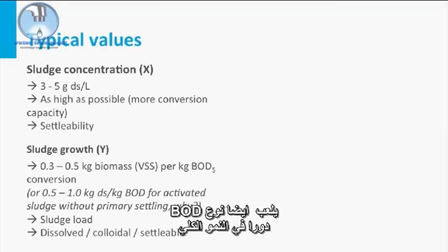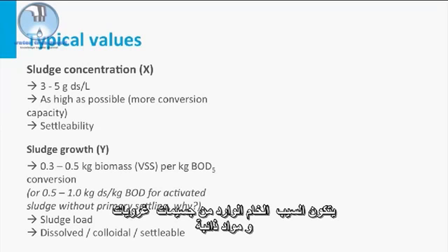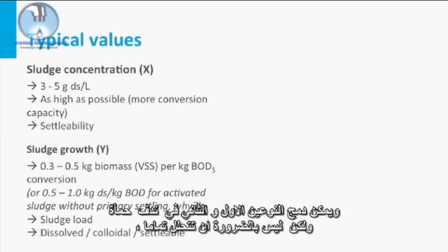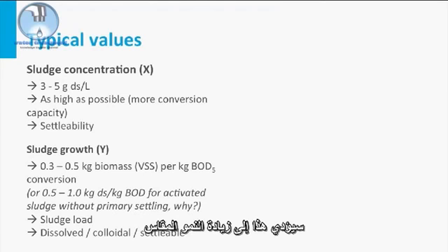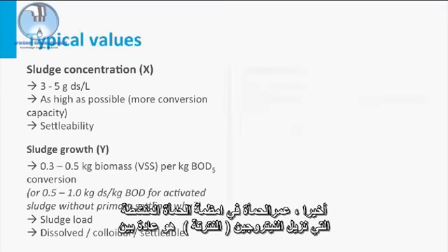Also, the type of BOD plays a role in the overall yield. Influent consists of particulate, colloidal and dissolved substrate. The first two can be incorporated in a sludge flock, but will not necessarily degrade completely. This will increase the measured yield.